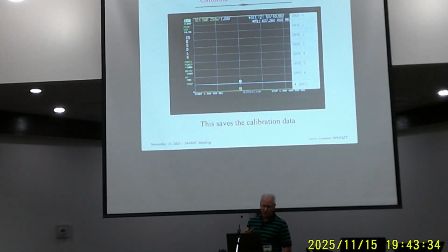If there's any questions, actually, if you want to sit down, if you're not absolutely totally sick of this by now, and if you're still awake, we can actually run through. I brought a little fake 5 megahertz dipole with me. So we can actually go through there and hook this up. We can run through setting the frequency range, doing the calibration, and actually taking an SWR plot of that. And you'll see that whole thing takes a few minutes. I mean, it's really quick to do. So that's all I really have on here.